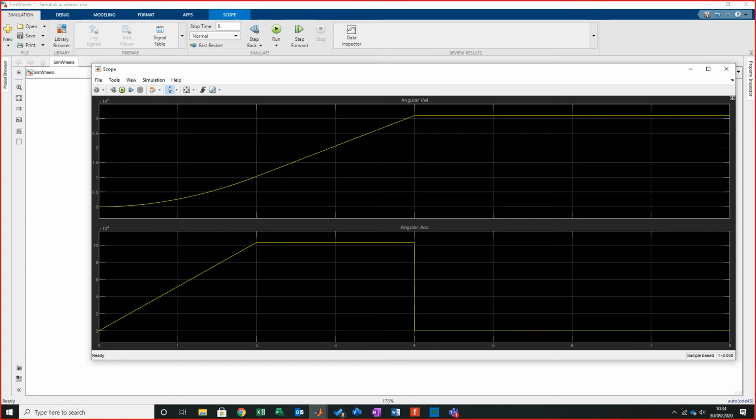If I run it, we get a strict increase on the acceleration. We get that initial momentum for the rise up to velocity. Then we're getting up to speed, and we get to the maximum velocity. Then acceleration drops because we set that particular point to 0, so there's no further acceleration going on. We run it to a certain speed and then it halts and drops straight back down.